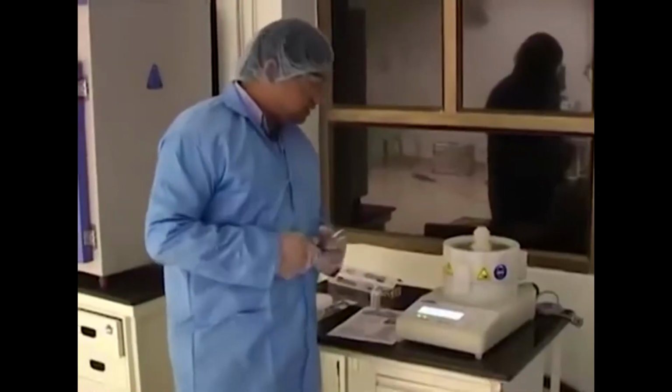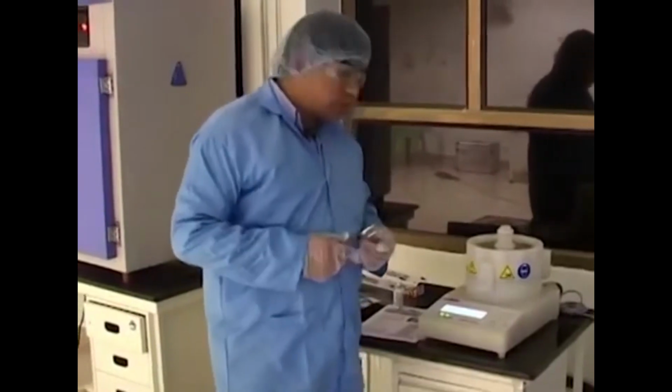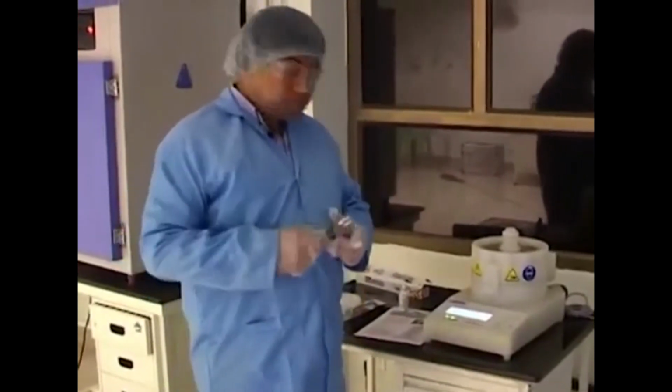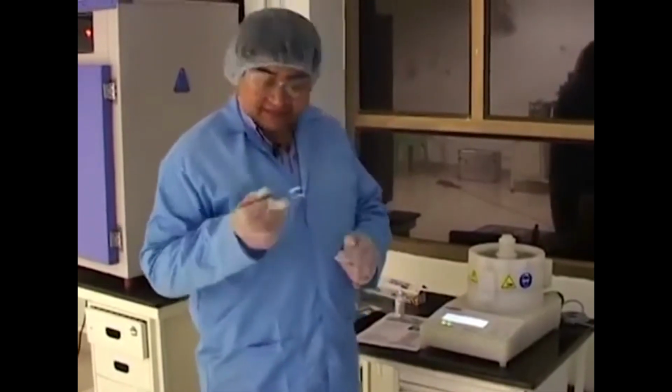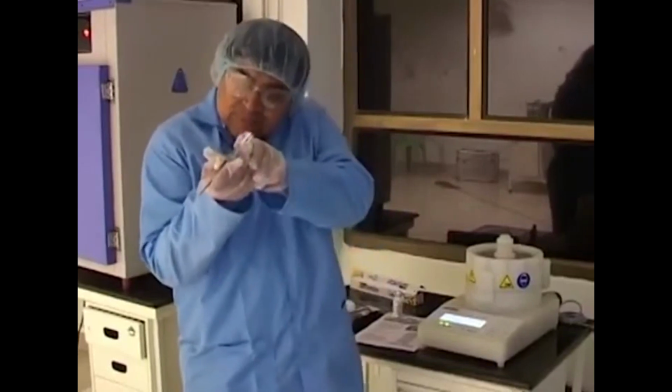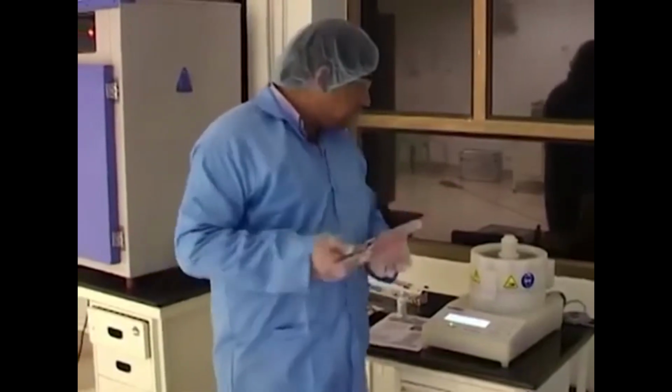Now the resist is actually spin coated, and we have to be very careful about removing the wafer. We have to hold it from a thin corner at the sides, because that is typically the area where there should not be any designs and structures. We will just use a little bit of tweezer space for holding it and be extremely careful about handling, because mind you, at this stage the resist is actually a kind of liquid in nature.